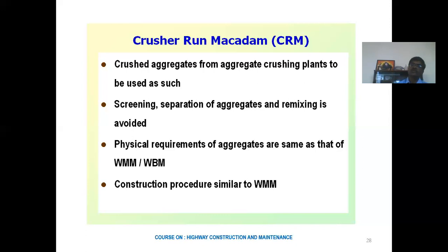There we are separating, that is screening, and then remixing the materials in wet mix macadam. In crusher run macadam, that screening, separation of aggregate and then remixing is avoided. That is the biggest advantage. Coming to the requirements, the physical requirements are the same as for other granular layers like wet mix macadam and WBM.